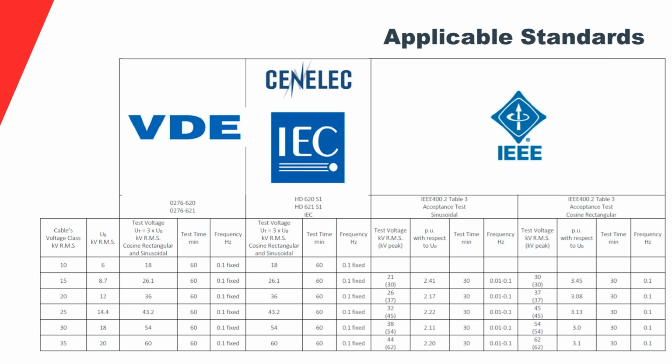All right, I've seen this question come through a couple of times. Is it acceptable to test more than one cable at a time? Yes, surely. Actually, this is the big benefit of having a large capacitance test set. If you're just after the VLF test and you don't try to turn it into a predictive test or gather more diagnostics information, it is actually the common practice around the world to parallel the 3 phases and get the VLF test out of the way. And only if it fails, then you have to do further investigation.